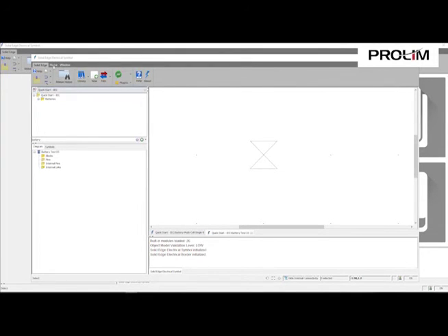So now I'm going to hop back over to the Home tab here where I've got all my drawing tools. I'm just going to create a simple little battery. And again, I want to use this insertion point as the 0 point for my little design. I'm going to pull it up this way, so that when I bring this symbol into the diagram, this bottom left-hand point is my origin point.